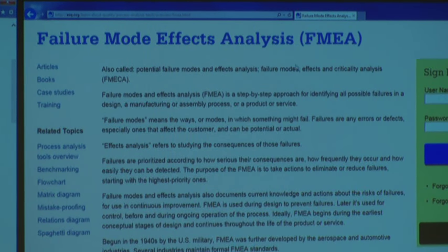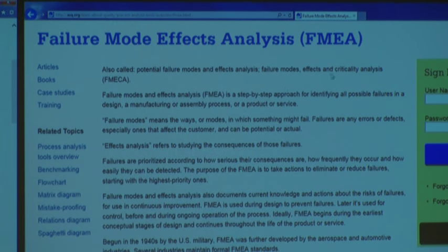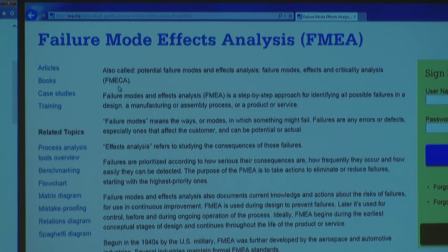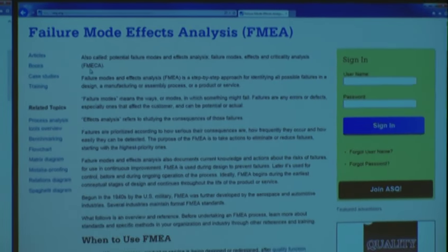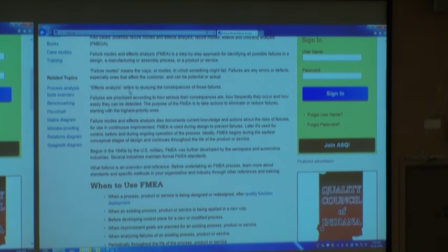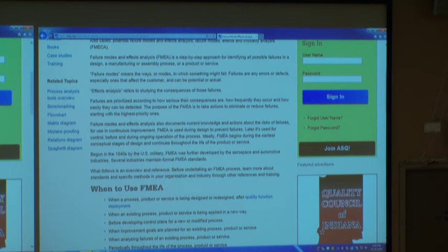But you can get some of the different things you might hear, like failure modes, effects and criticality analysis. And you see that a lot too, FMECA. People call it a FMEA. So if you move on here in industry and you hear somebody say, we need to do a FMEA or a PFMEA or a FEMA or PFEMA or DFEMA, these are all variants of the same thing. So the P would be process, the D is design. Sometimes they put in the C, sometimes they don't. The C is just criticality, so how important is it? But a very similar mode of doing an analysis. And you're looking at the consequence of failures. So that's the effect part again.